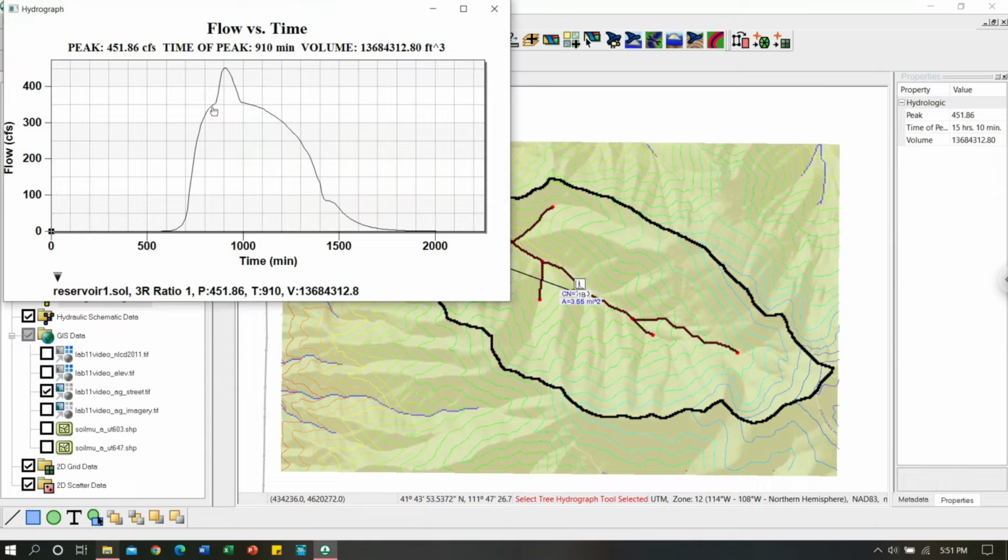and the amount of flow increases, then suddenly there's this dramatic jump in flow. This is when my reservoir has backed up enough water that it has started to reach the elevation of the spillway. So instead of continuing to increase head on my orifice, the lower outlets, more volume of water can use the spillway. This decreases my peak flow a little bit.